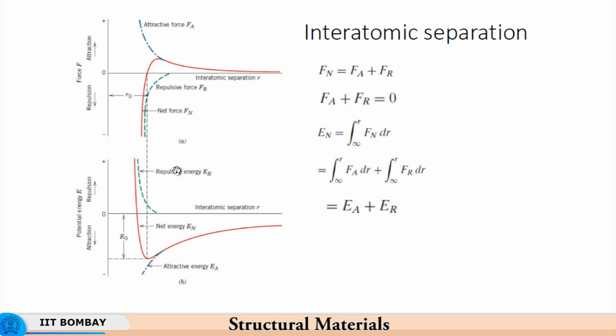So, here this R naught is the initial stable position, and you can displace it to another by another R naught, but then the energy required will have to go up an energy hill and then come down again to practically 0 energy at the next stable position. So, this way you can move the atoms permanently by applying a sufficiently large force, and that will be seen as plastic deformation.